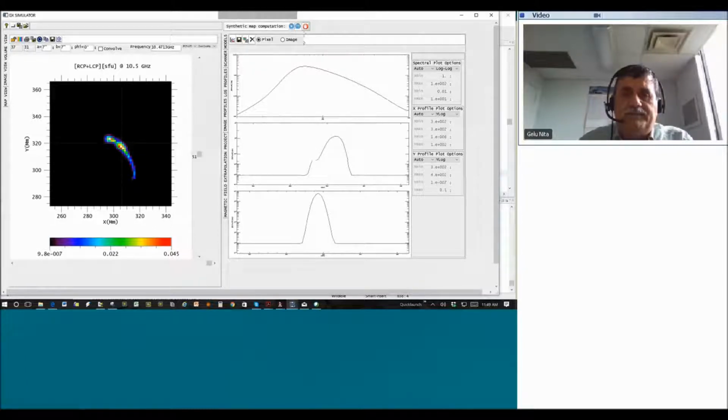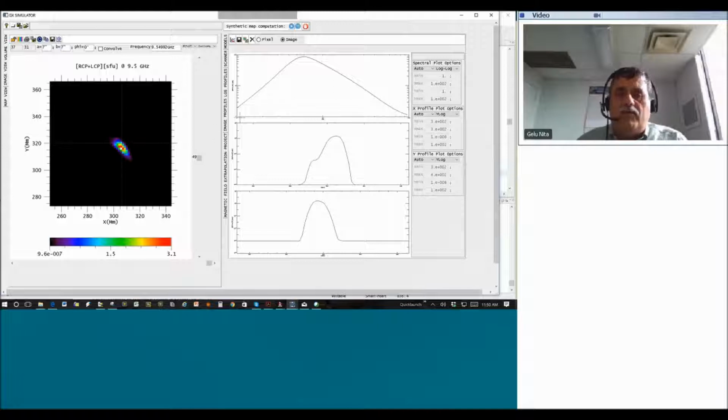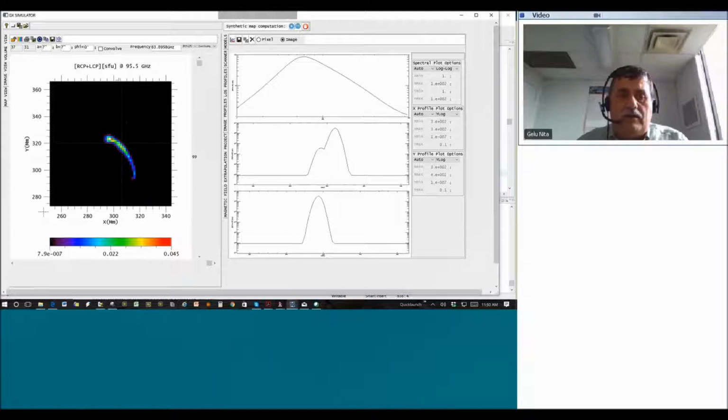And when you do that, I know that you have to finish in 5 minutes, so I'll finish, don't worry, but I just want to change here image. Okay, so this is the spectrum. Now if I change frequency, this spectrum won't change, because for each frequency it is just one number. And we add up everything, all this added together gives you this point here. When we go to 1 gigahertz, all this added together gives you this much. And the peak is somewhere here at about 10 gigahertz. So this is where the emission is stronger.